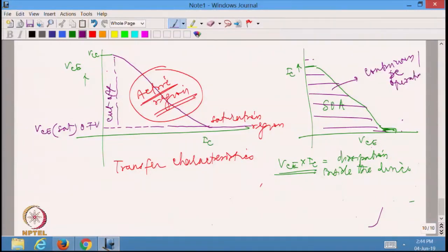But if I am going to have it in pulsed operation, for some time I am going to turn it on and some time I am going to turn it off, then probably I can increase the limit slightly. So, this is essentially corresponding to pulsed operation. If I am going to have some pulses only, then I would be able to dissipate more heat because every now and then my device gets some rest.